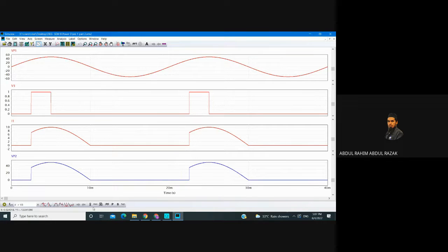It is switched on by device triggering, and switched off by the current when it is reverse biased. Only when the current is reverse biased will it turn off. When it turns on depends on the time that the device is triggered. When it turns off depends on when the current is reverse biased. That is the behavior of the semi-control device. Later on we will do more experiments to better understand the behavior of the devices, the difference of the devices.